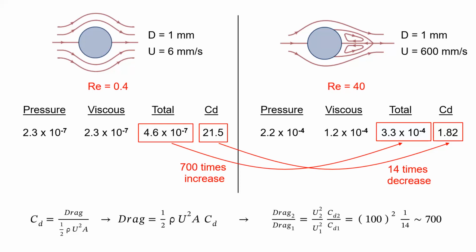When you compare the drag forces of two different Reynolds number cases, it is important to know how the Reynolds number is changed. Is it due to speed change, or viscosity change, or maybe diameter change. In each case, the change in drag force would be different. But, in all those cases, the change in drag coefficient would be the same. That is why, reporting the drag coefficient, instead of the drag force, is more logical. One should always calculate the drag coefficient first, and then switch to the drag force if necessary.